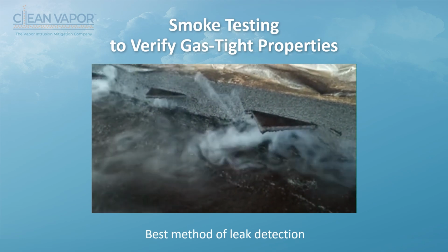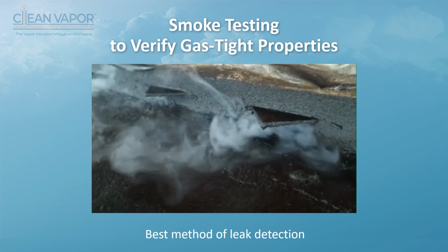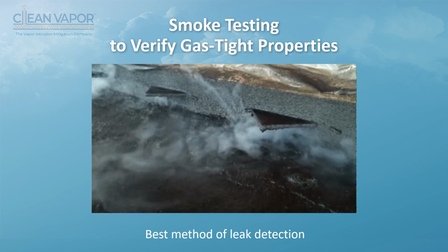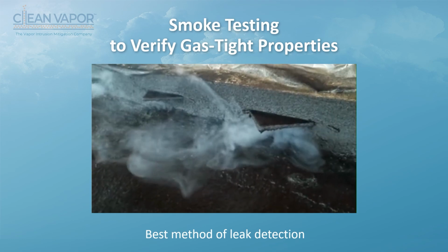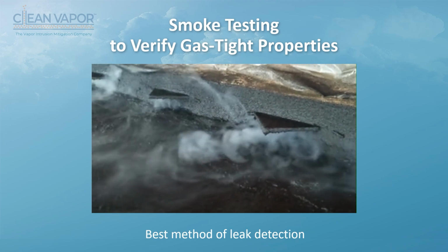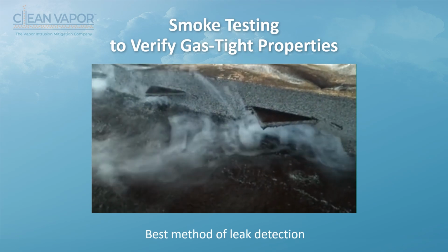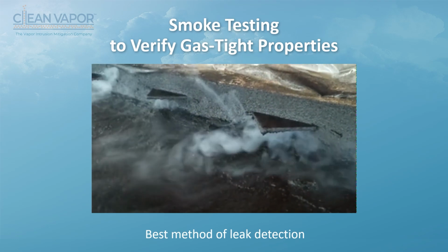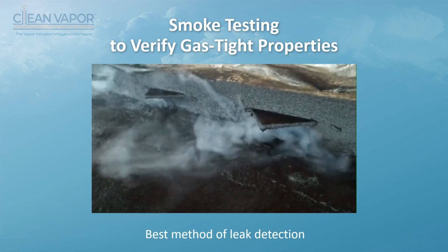And this was cut open for the demonstration of this video, but this is the absolute way to go. And then somebody signs off on it that this column area of the building by that column area of the building has passed a smoke test on this day. And that will give you the record that you need. You hold on to that because that goes into your commissioning documents at the end. So this is what a smoke test looks like.